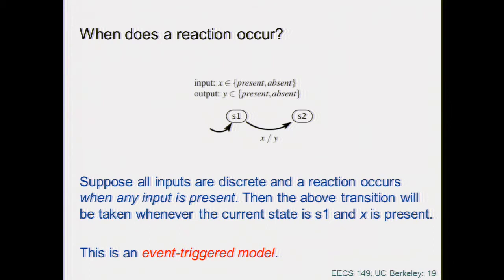What happens is that the transition is taken, some input is changed, and time has reached a certain value, right? And so that is time trigger. So I can only make a transition at specified times, right? So in the previous example, I can still find a way of tricking the system.